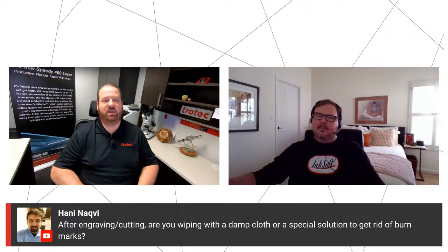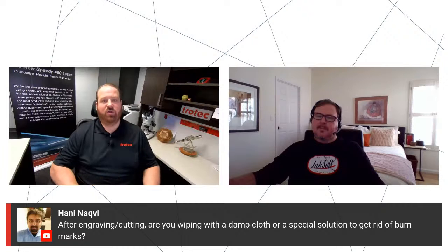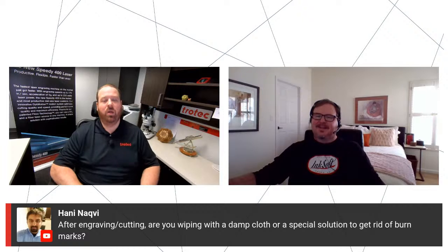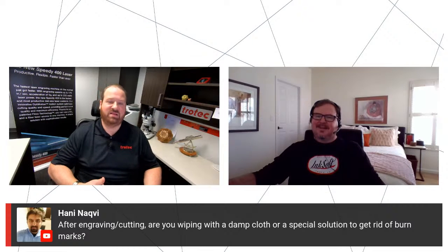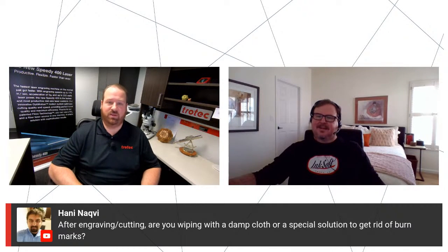Like the wood that you saw me do that with, the wood has been finished with a clear coat. The clear coating was put on the wood before it was engraved, and then it will wipe right off. If that wood does not have a clear coat, then that process won't work. On plastics and other materials, yes, just a simple cloth. If you do get some staining and residue, you can use any type of cleaner based on what material you're working with. So you've got to be careful too.